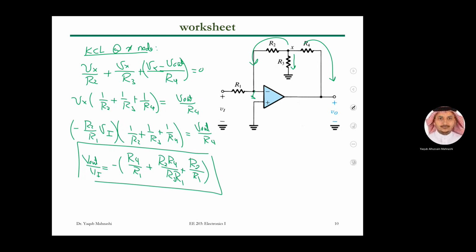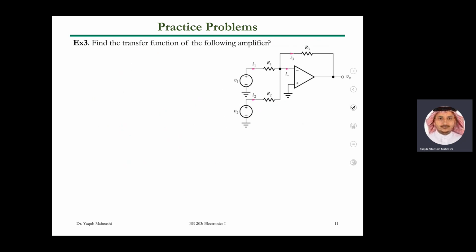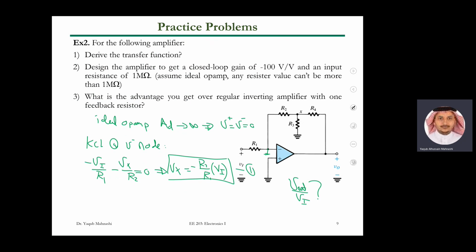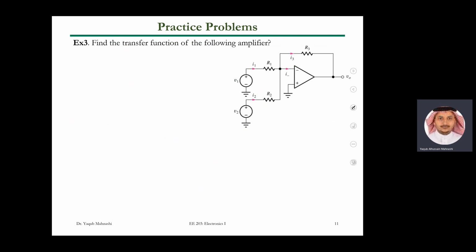Oh, yeah, R2. Okay? And there is a design associated with this. I will leave it to you. This comes back to me later. You have a gain of 100 volts per volt, and you have an input impedance. Let's say, Shabab, it is R1. And let's keep R1 to be 100K for simplicity, and this one to be 10 megs. So then you have room to maneuver here. Okay. So if you have these values, try to put them there, and let's see if you can get the results right. Okay, we'll stop here, inshallah, next time.